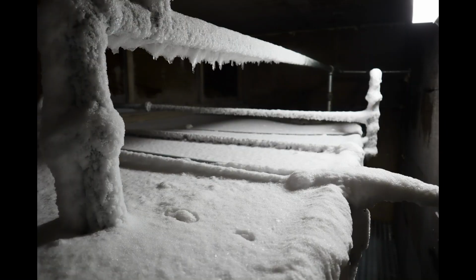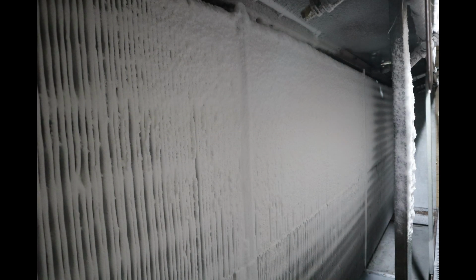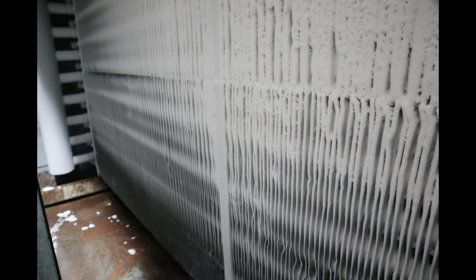As air passes through the finned surface, water vapor will freeze on the surface of the coil. This frost decreases the evaporator capacity for two reasons. First, it reduces the distance between fins, which restricts airflow. Less airflow results in less heat transfer. Second, the frost acts as an insulator, which negatively impacts the heat transfer capability of the evaporator. Because of this phenomenon, in most situations, air cooling evaporators must be periodically defrosted.